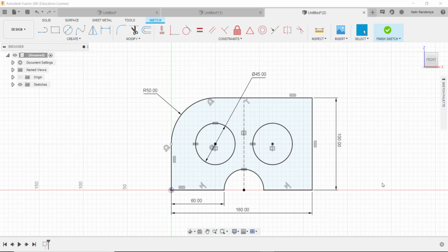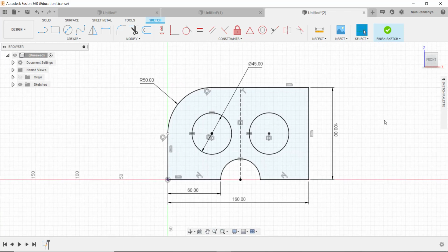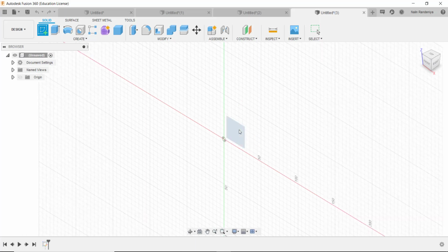All right, let's start with this drawing I gave you as an exercise. Before I come to that, I'll explain some of the constraints I used here. There will be something new I did not explain last video: these symmetry and concentric constraints. So let me open up a new sketch as usual and explain those constraints.